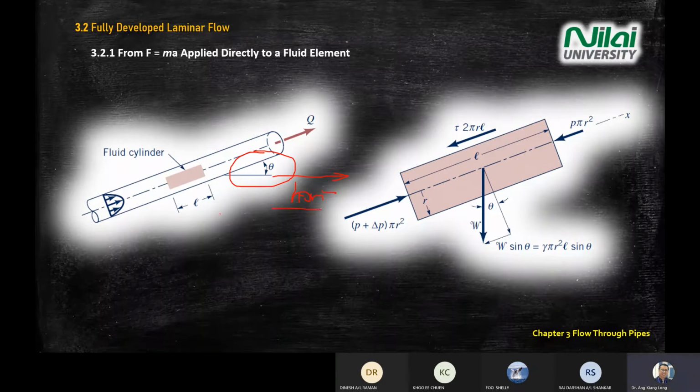Okay, horizontal. The same pipe characteristic that we discussed previously, the only difference is now we change the angle. When you change the angle, something changes in the equation. As you can see, if you change the angle, a W component takes place. This one must be added to your equilibrium equation of force, where all the forces equal 0. So when there is an angle with the horizontal, remember there is a W, or weight of the fluid, happening.